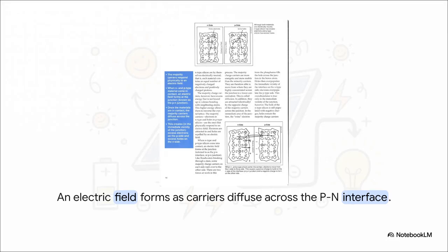Now, as a result of that intense diffusion, by leaving those charged ions behind, a positive charge builds up on the N side of the junction and a negative charge builds up on the P side. This spatial separation of static charges basically acts like a battery built right into the crystal itself. It establishes an incredibly powerful, permanent internal electric field across the junction. This field acts as a sort of electrostatic barrier, preventing any more electrons from crossing over. It's a one-way turnstile, and it is perfectly primed for action.